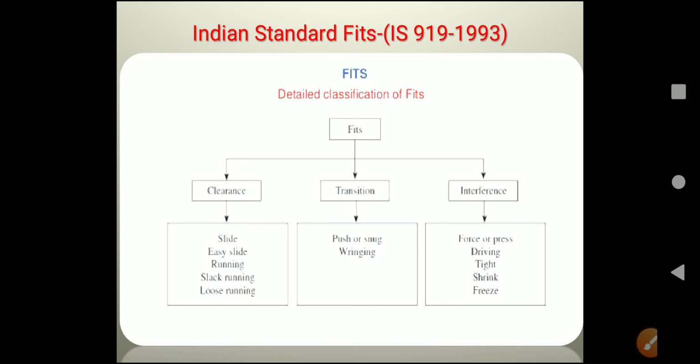In the second type, the transition fit, it is classified into push or snug type and wringing fit. And finally, the interference fit is further classified into force or press fit, driving fit, tight fit, shrink fit, and freeze fit. So in detail, we are going to study the types of fits and their applications.